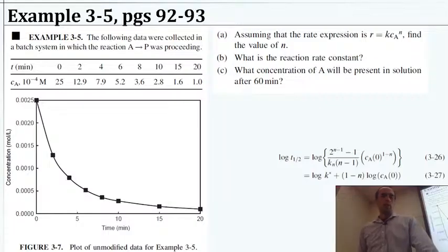Okay, so today we're going to talk a bit about reactor analysis from the standpoint of, okay, how efficient is it? How do we describe that? How do we get some sort of efficiency term for how well it's performing, or how much we're removing as a function of hydraulic residence time, as a function of the rate constants. So, piecing together the different things we've looked at so far, and doing a little bit of practice, just working through a few examples of that type of looking at an equation or looking at a system.